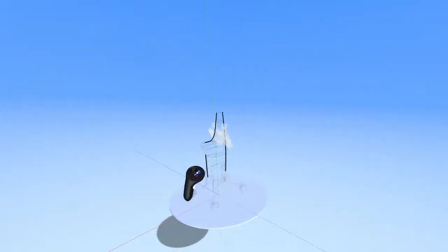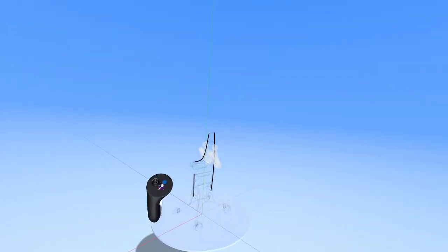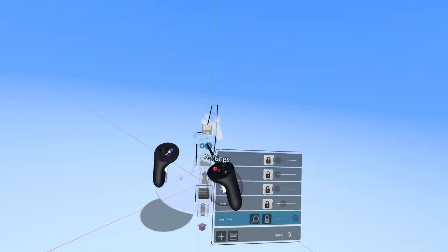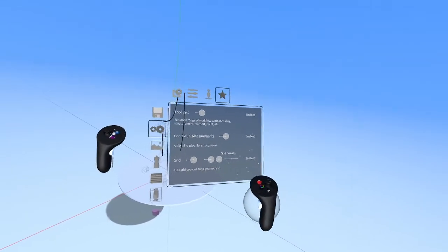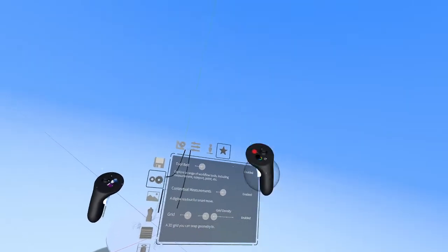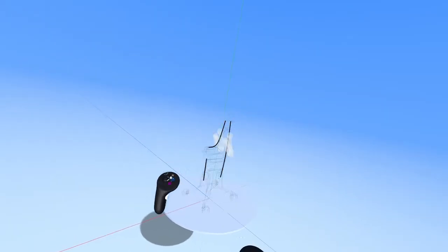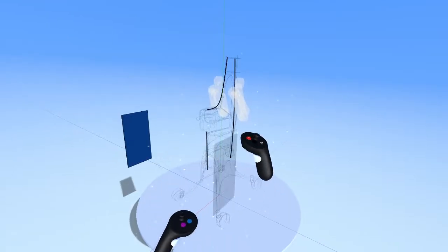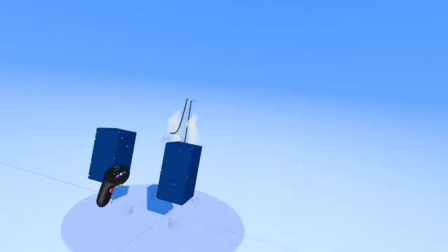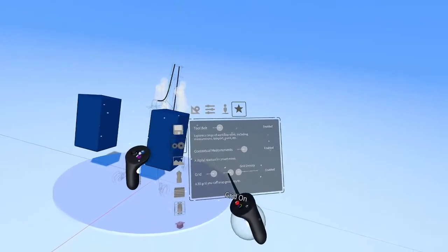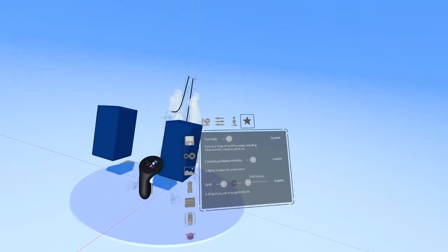So what we'll use here is another beta feature: settings, beta, grid tool. So let's turn on the grid. And once you turn it on, you see all these floating dots around. That is the grid. And then you can click and drop in a shape very easily, and it's placed very precisely. Now, that's all we need the grid for. We can come in here again and turn it off.